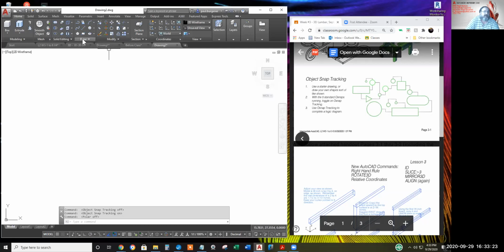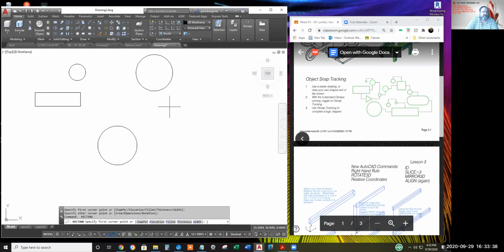To keep up with me, again, I won't collect this, but we'll draw a few circles and a few rectangles. Where's rectangle? Now, say I want to draw a line for a logic or a chemistry or process, the electrical diagram. But anyway, I want to draw a line from this quadrant, come straight to the right, and stop it absolutely perfectly over the midpoint of this rectangle. Hit escape. You with me?